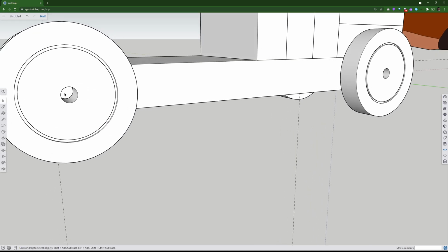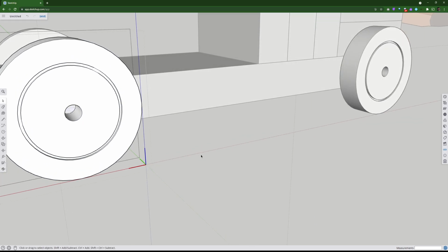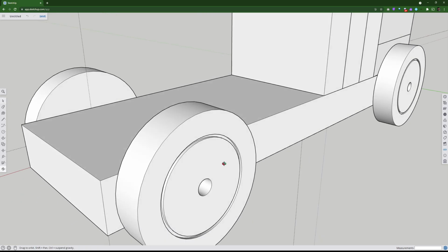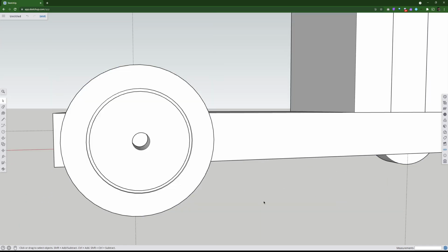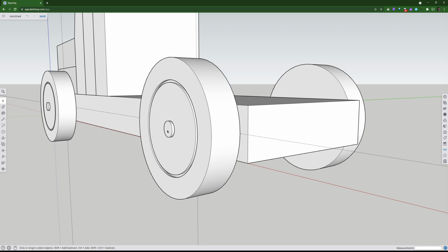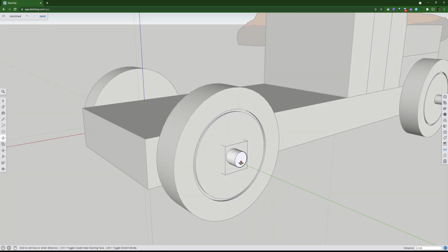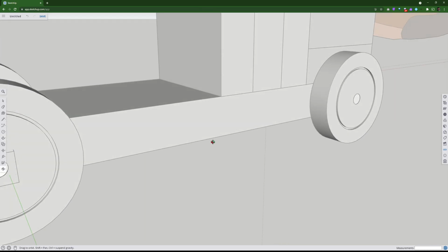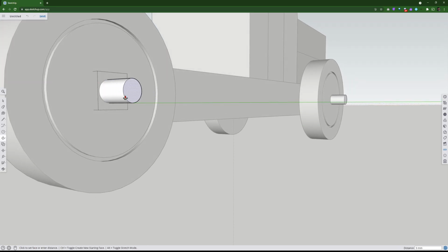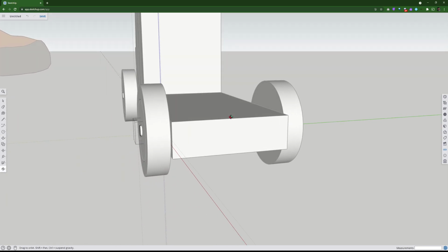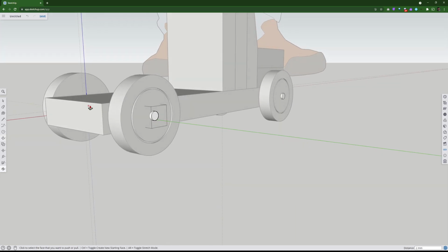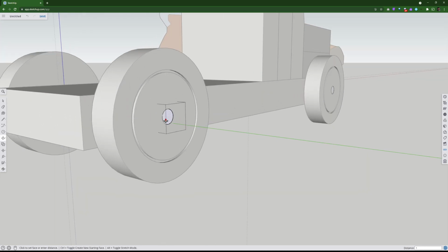Now, did you notice that when I double click on that one there, I want to get the actual axle. What I'll do, because I can't pick it, I'll double click on here. Now I've got that. And then I'll pick push pull, bring it up to there, and then I'll bring it out 2 mil. Now you notice how the other one is moving at the same time because of the one component. I'm going to bring that face 2 mil away from here. Or did I do one? I did one, so I'll go back 1 mil.